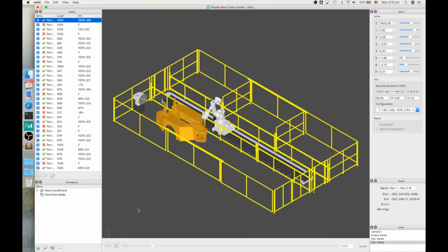All of the motions that our software generates are collision-free, singularity-free, and include touch sense calibration motions without any additional human effort. Here it is performing the touch sense, and then it will return to the start of the weld to perform the welding operation.